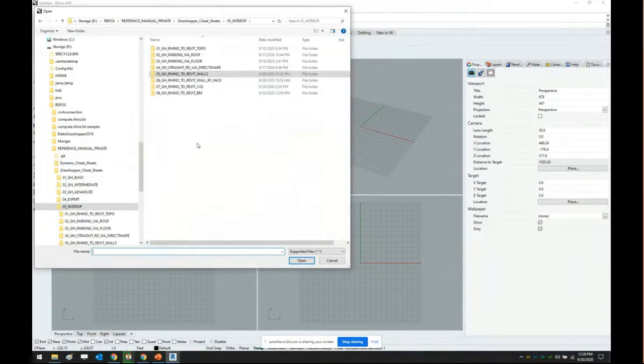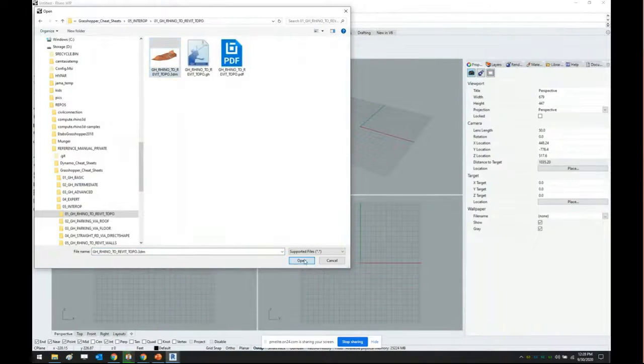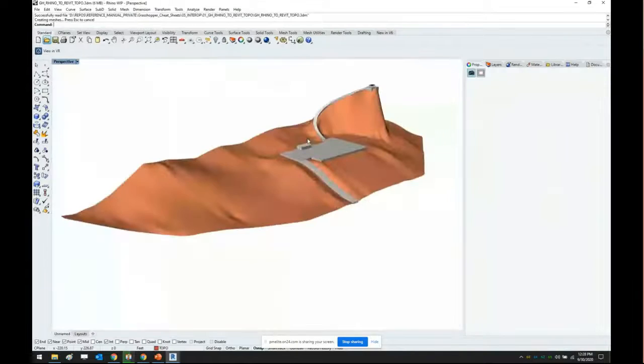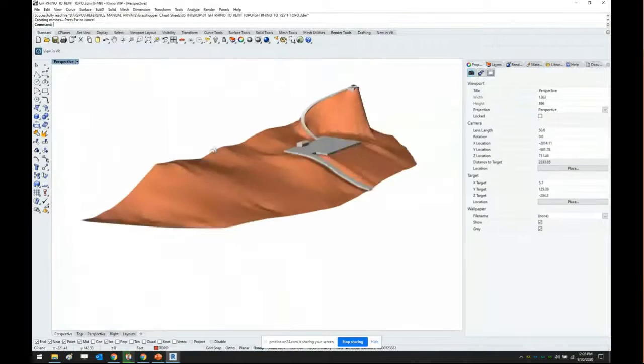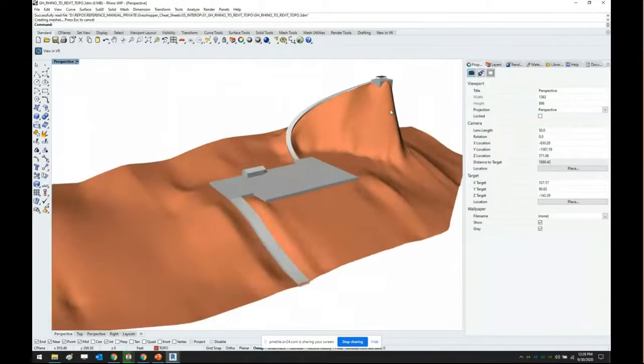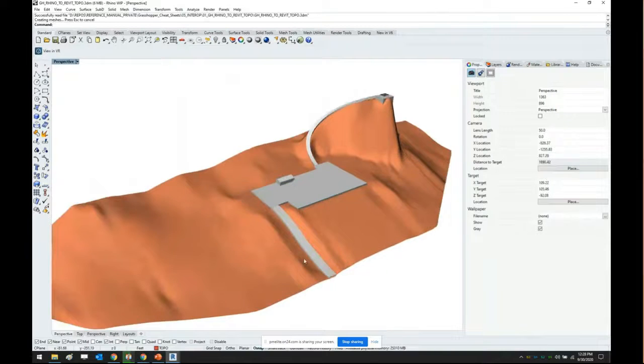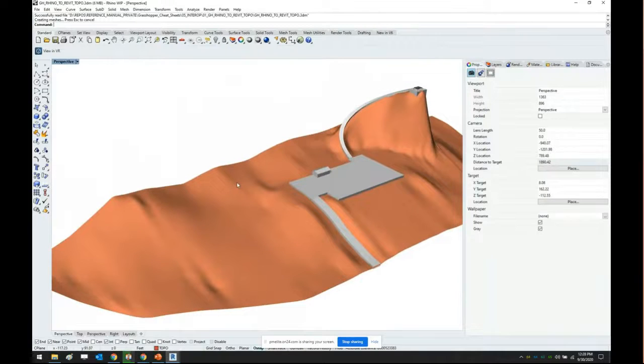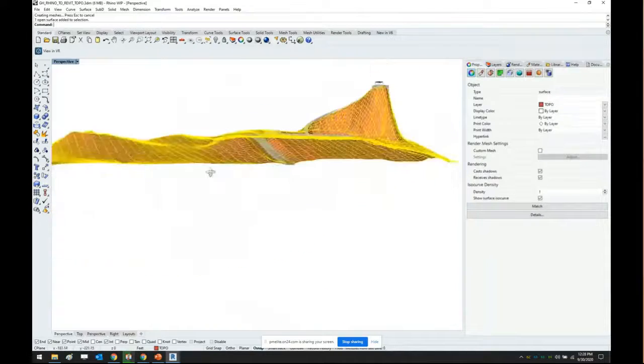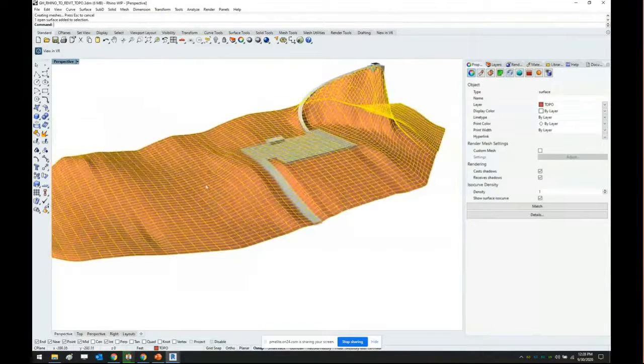Here we go. This is the model we're working with. This is the model that was done, maybe by you, maybe by your exterior team, whatever. But you have this model, and now you need to get this information into Revit. So what decisions do you need to make? Let's talk about this big surface right here. This is a BREP surface inside of Rhino. How do we want to get this information into Revit? Let's just talk about this topo surface right now.